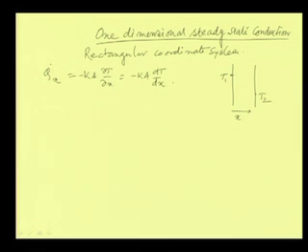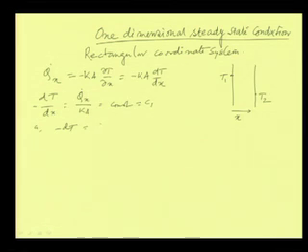At steady state the heat transfer rate should be constant. So, q dot x is a constant quantity, therefore we can write that dT by dx equals q dot x by k into A, so minus dT is equal to some constant, say C1, into dx.